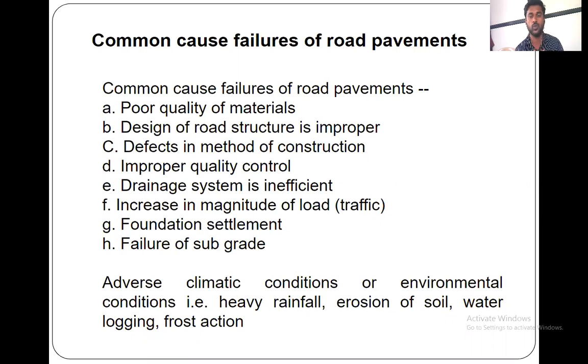Ultimately, the load carrying capacity of that soil is less, so cracks will appear on the road because of failure, since the CBR, that is the load carrying capacity, and the bearing capacity of the soil are very low.